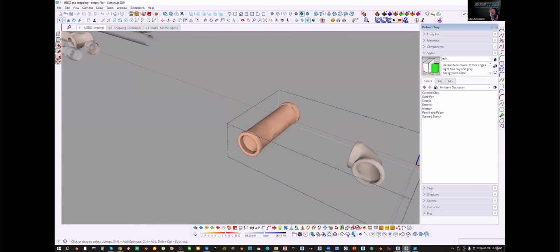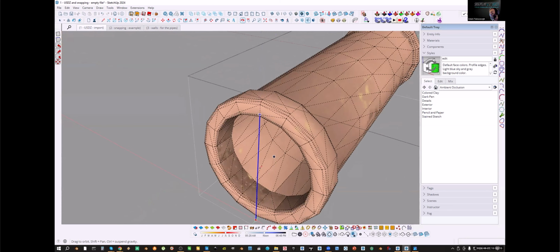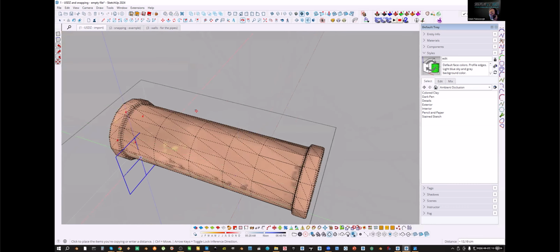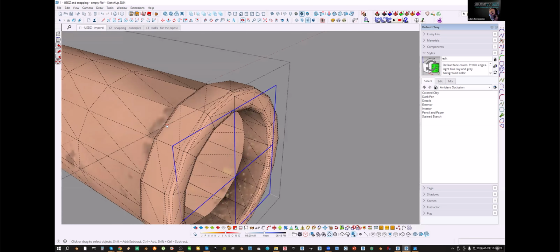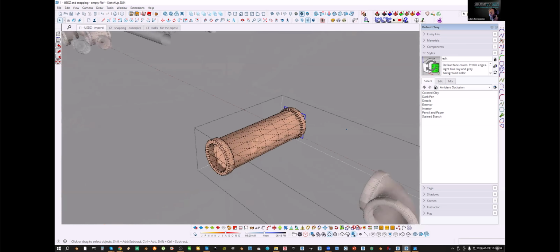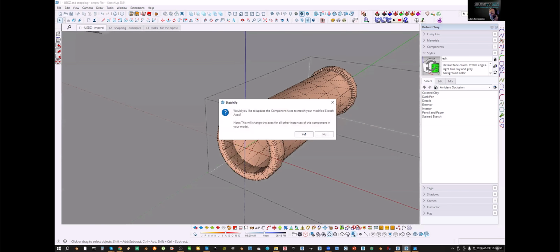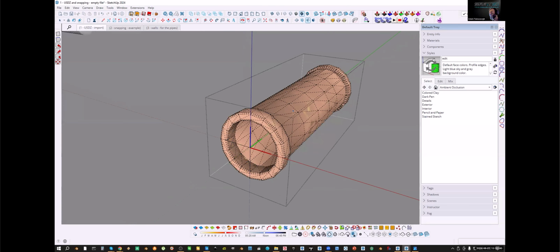And now I'll double click, and it would be very handy if I add some guidelines. So in the hidden geometry, let me quickly modify it 90 degrees with the rotation and copy guidelines. I'm going to make that a component. No names this time, just Enter. Okay. And here we have the object prepared. I can move the axis also just for a clearer model. I'll accept the axis. And now going back.